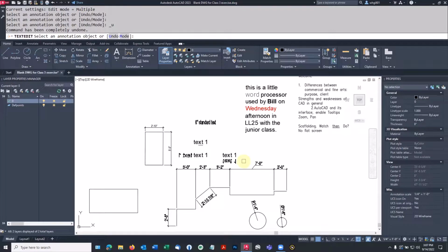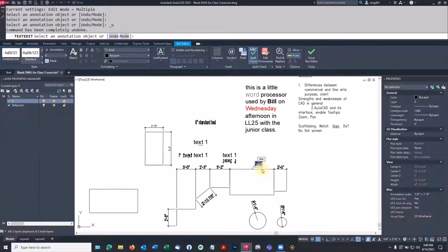We're going to keep on working on your apartment drawings with casework and fixtures and furniture and like that. You can change all your existing dimensions to your new dimension style. A way you can do that is select a dimension, Control C, go into your apartment drawing and paste it. Then that dimension will bring its style with it, and then you can apply the style to all the others.